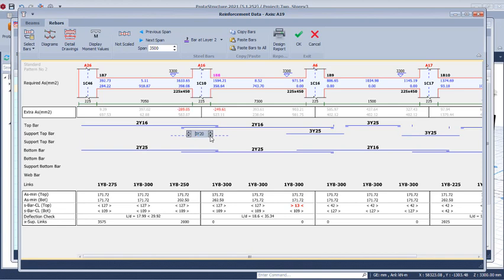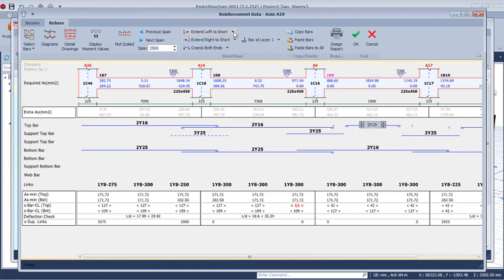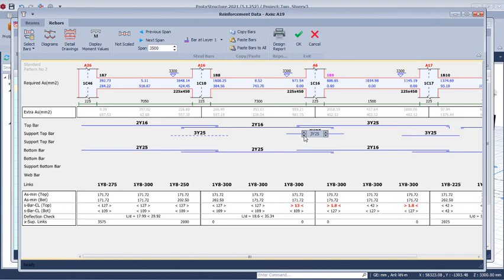Okay, so let's reduce this. You see, if you reduce it, it's failing already, so you increase the limit at 25. So you can see the length of the span of the beam, which is 7.05 meters. Here it is 7.3. That is why it is selecting these high diameters of reinforcement. So you have to do the same thing here. Lap it over there, also lap it over there. Then try to reduce here, and then increase here.